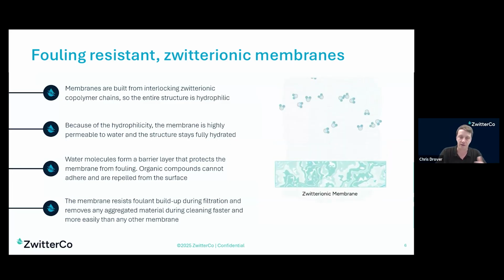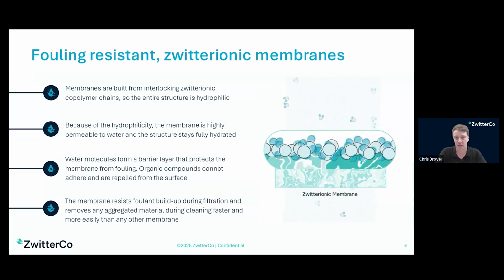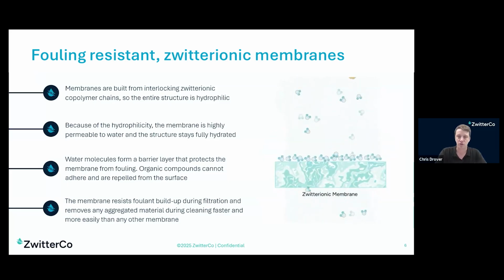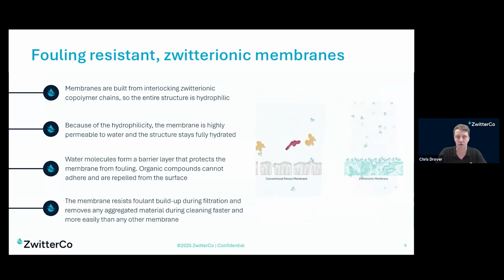One of those, and you'll see this in the video that's playing on the screen, is that the attraction between zwitterions and water is so strong that these materials almost form a hydration layer or shell. And this water layer is really tightly bound to the zwitterionic chemistry, and it effectively prevents oil and grease and other foulants or proteins from contacting or sticking to the surface.